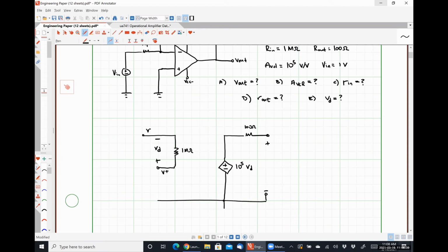So everything I've done up to this point is just the practical op-amp model where I've swapped the polarity on my input resistance. Now I need to go through and actually connect things. So for instance, between my non-inverting input terminal and ground, right here, I have a short circuit. So I'm going to short that to ground. Between my inverting input terminal and ground, I see that resistor R1 in series with my voltage source Vin.